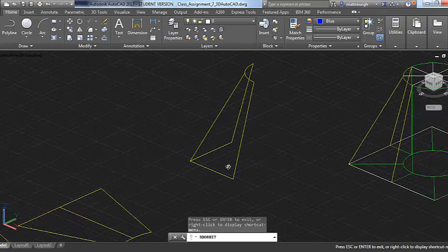Sometimes as a press brake operator, when you do that, you end up getting it round on top, but it still isn't turned over 90 degrees, and I have to move my part in my press brake to hit it on the square end and turn it 90 without making the round go out of round. So there's ways to get around that.